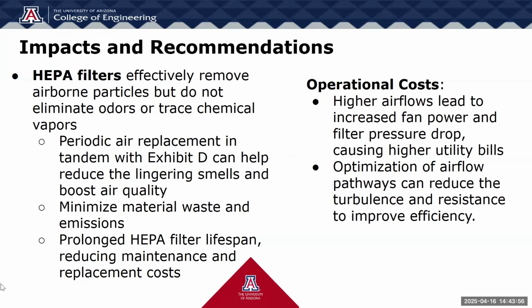In addition to optimizing airflow for cleanroom standards, we also considered several broader impacts, especially those tied to cost and sustainability. Starting with HEPA filtration, while HEPA filters are highly effective at removing particulates, they do not address odors or low-level chemical vapors. Over time, these can accumulate in the air. To mitigate this, we recommend scheduled air replacement every few days or weeks, which not only improves air freshness, but may also extend filter life. This helps reduce operational costs tied to frequent filter replacement.